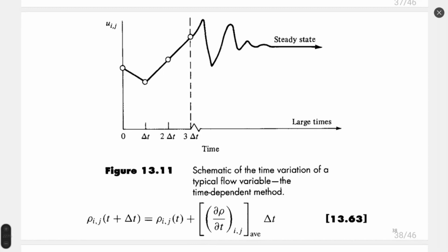We already know, right? Simulating an airfoil, we can choose whether it is transient or stationary. If you choose transient, you will see that convergence, which is also shown on figure 11, is not a fast process. You can observe a decrease or increase of residuals. Here on figure 11, the parameter is different from residuals. It's not residuals by itself. It's some flow property, or stabilization of a flow property in time. And residuals, which ANSYS is showing, is a derivative of this curve.